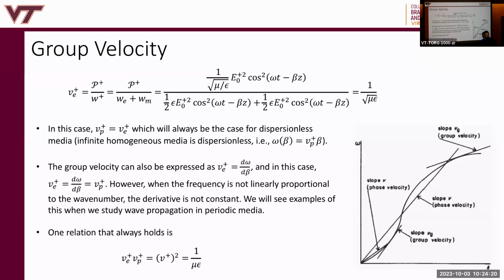So there are two things in electromagnetic theory, right? There's guided waves, where you have a waveguide, which we'll study a little bit more next semester. You can direct energy in a particular direction using a waveguide, which has very complex properties. You have to solve for the wave number of the guided mode, and it's usually frequency dependent, and there's dispersion and all this. And this is the most important curve for guided modes. You need to know the wave number of the waves that travel along that waveguide as a function of frequency. Once you have this curve, you have almost all the information you need to analyze the wave propagation in guided modes. And the other one is called scattering.